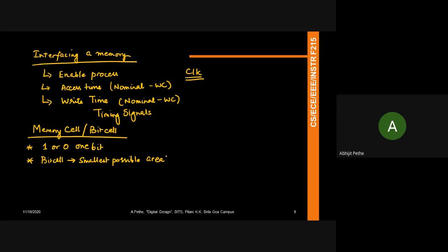Okay. And also we know that if you're going to use the bit cell in your entire large memory, you want to ensure that the bit cell has an enable signal and it has a read write signal, right? Basically, these two signals are used to either enable the bit cell or to tell the bit cell what it is that we want to do with it, whether we want to read the data off the bit cell or write new data into this bit cell.